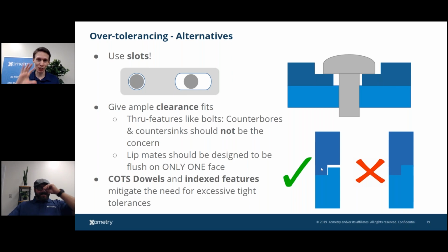As I said, again, it's so much cheaper than making a custom, vertical protrusion feature at a super tight tolerance. Drilling a hole with a reamer and pressing in a dowel pin is standard practice. It's very successful, and sometimes to get those critical tight tolerance mates, you could make those dowel pins your index features, and then use fasteners with a looser tolerance to hold everything together. So I really recommend thinking outside of the box. Sometimes think about integration and assembly. Using these off-the-shelf features, they're off-the-shelf for a reason, because they are common and they are useful.